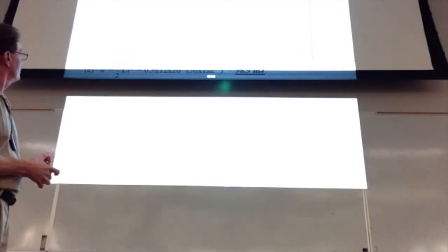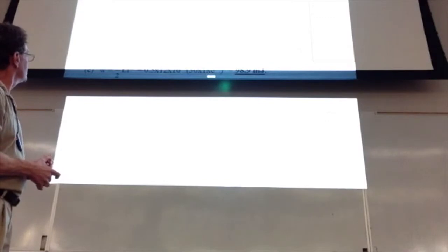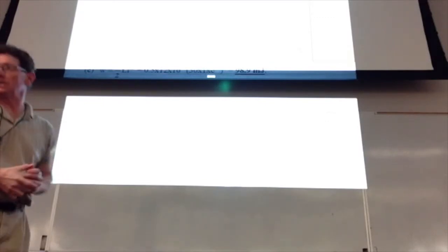And for the final one, if we calculate 1/2 L i squared, you get around 98.9 millijoules. Okay? That's the actual energy that's being stored at t equals 1 second. Okay?